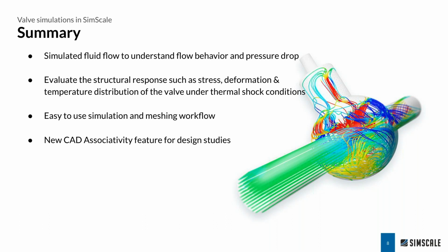we covered how we can look at the fluid flow and simulating that to understand the flow behavior within a globe valve type of application, and understanding how we can look at the pressure drop within the system. We've also looked at the structural response, looking at stress, deformation, and temperature distributions of the valve under the thermal shock conditions.